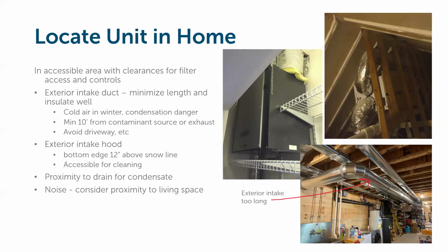So go ahead. You have a quick question here, Mark, going back on the defrost cycle. William was curious if the ERV versus HRV material allows for condensing. In an HRV, that core material is either going to be plastic or aluminum. An HRV, as we covered last time, does not transfer any moisture in the system at all. So when you get condensation, it's going to freeze, or condensation in general has to go out through a drain.